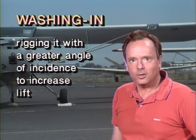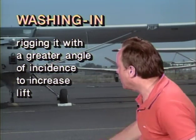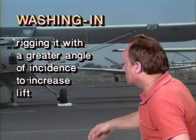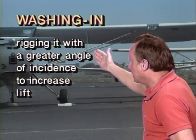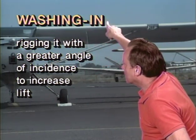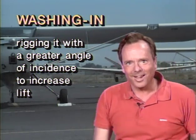Well, what would be washing in of the wing? And this has nothing to do with cleaning the wing at all. Washing in of the wing is done by rigging it with a greater angle of incidence to increase the lift, and that's called washing in. So if you have any trouble remembering it, wash in increases lift. Wash in increases lift. You got it. I know you had it right there.